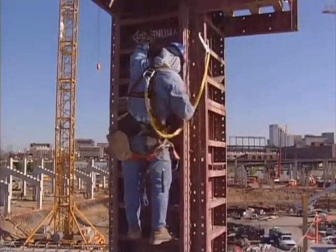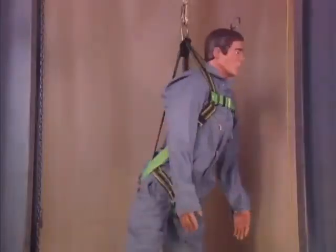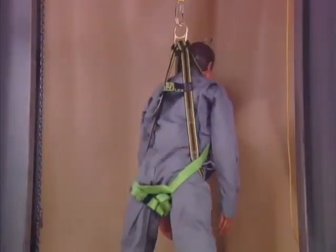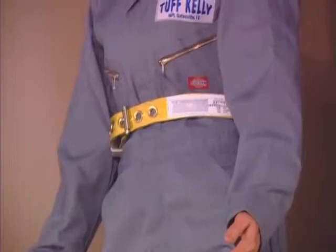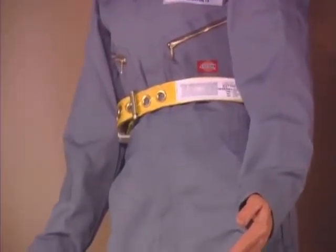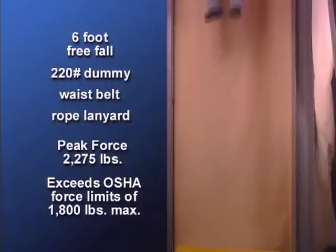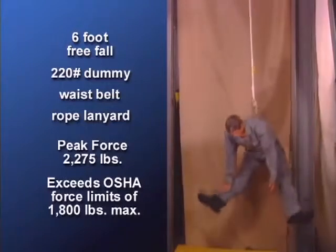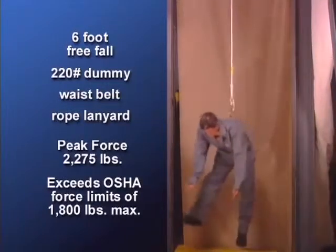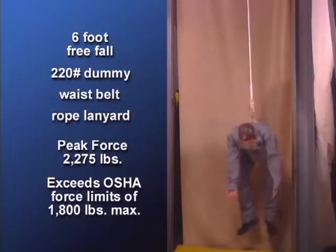The most basic item of fall protection equipment is the full-body harness. A full-body harness distributes fall forces throughout the body, thus reducing the chance of injury. Body belts are not recommended for fall arrest. In addition, most regulations governing fall protection prohibit the use of belts. In this drop test, a dummy is dropped into a body belt. Note how the fall forces were concentrated on the abdomen. Such forces concentrated on the abdomen could cause serious internal injuries.